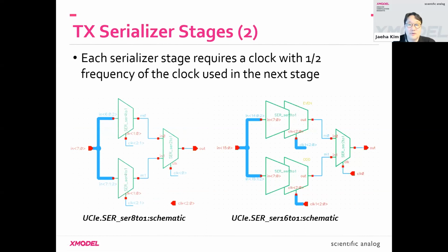One is it works at really high frequency in the end, like it will generate 32 gigahertz output at maximum. But also each stage will require a different clock frequency. So the clock domain crossing is very tricky to handle in typical synthesis tools, and so this will be done in a custom fashion.